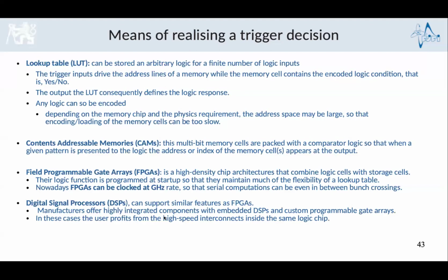And okay, for electronics, and how they are used to design some trigger systems. One of the ways is to use lookup tables. That is a single memory where you can put any kind of combination of conditions in the memory.